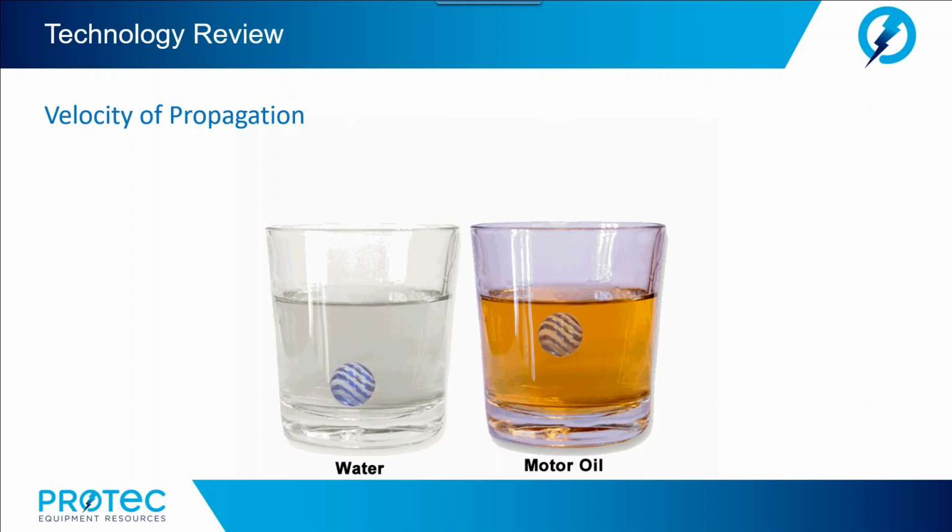Age of the cable will also influence the velocity of propagation, as will temperature and possible moisture content or moisture ingress inside the cable. With telecommunication cables such as twisted pair, the wire position inside the cable will have an influence on the velocity of propagation. And also cable manufacturer. For instance, composition of insulation material and any additives that are being used will all have influences or be factors in the velocity of propagation.